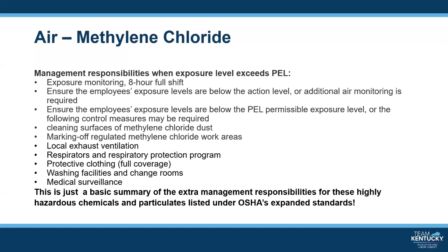That could be cleaning surfaces of methylene chloride dust, marking off regulated methylene chloride work areas, may require local exhaust ventilation, may require respirators and a respiratory protection program, may require protective clothing, that's full coverage clothing, may require washing facilities and change rooms, and it may require medical surveillance of the employees. This is just a basic summary of these extra requirements.